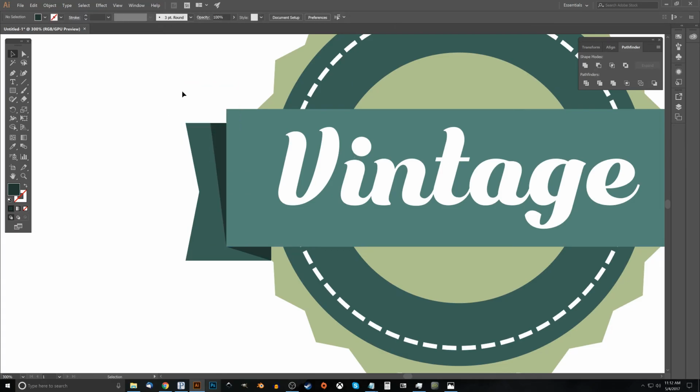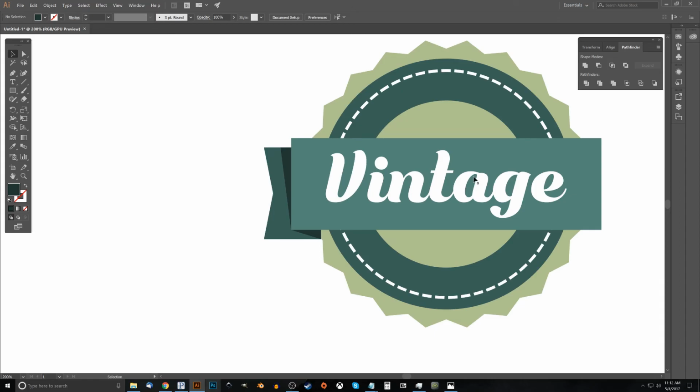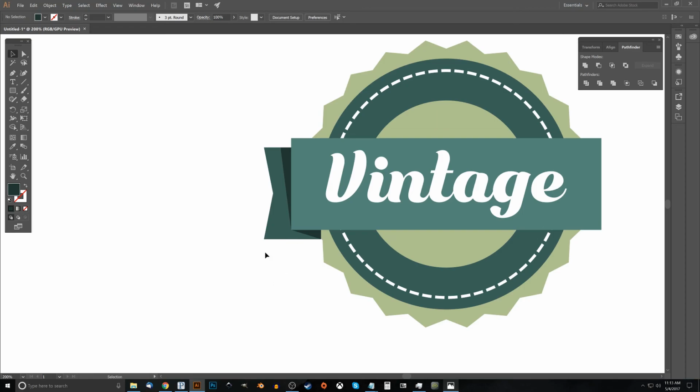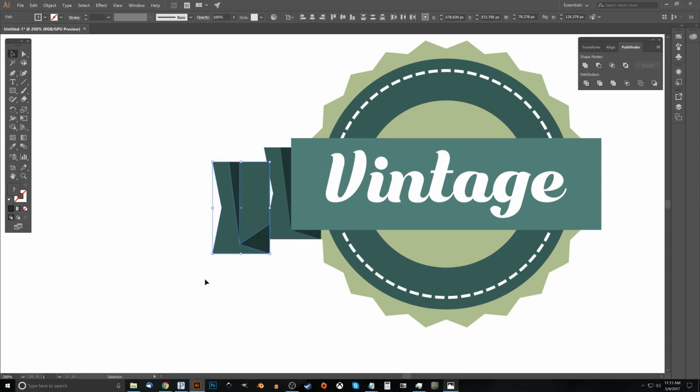Now we can click off of that to deselect everything. And let me zoom out a little bit. I'm just going to hold Alt and roll down the mouse wheel maybe once like that. What we want to do now is create a duplicate of this little area and flip it around and put it over here, because that's what I did for the thumbnail here. So to do that, I'm going to click on all three of those objects first. First, I'll click on this one with the Select tool, hold Shift, click on this one, and while still holding Shift, click on that one. And then I'm going to hold Alt and click and drag to create a duplicate copy of that.